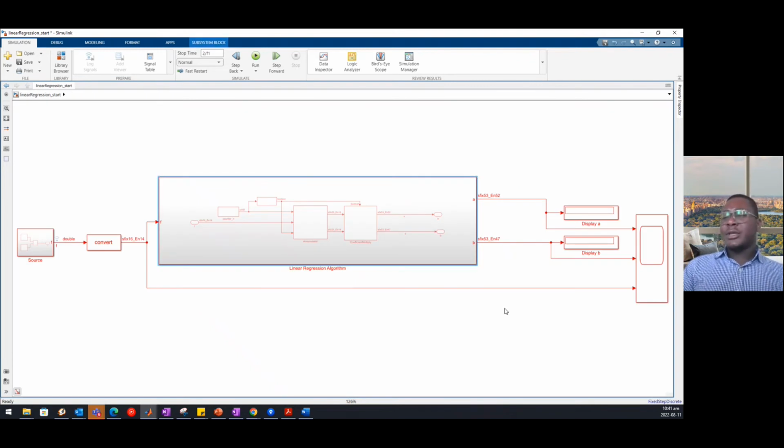One thing to note is that we have an input of 16 word length, but the output is actually 53 word length. This is a growth of more than 300%, and this is what happens when we manually convert these data types into fixed point. I'll show you a trick in the second part, where we'll look at the Fixed-Point Tool to convert the model into fixed point. This is where it actually helps. But for now, we'll go ahead and generate code for this subsystem.